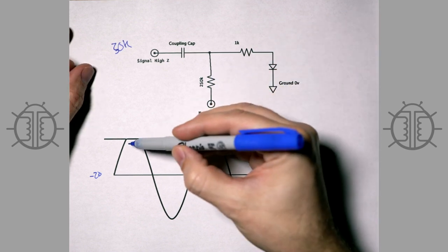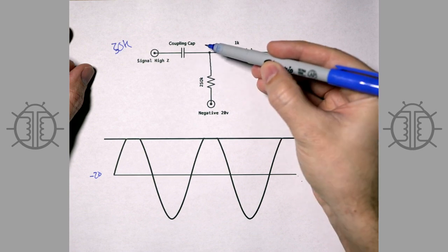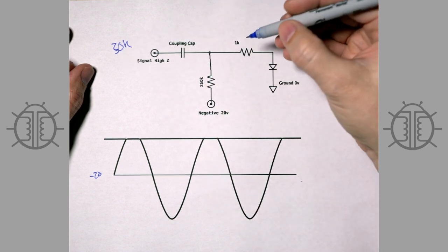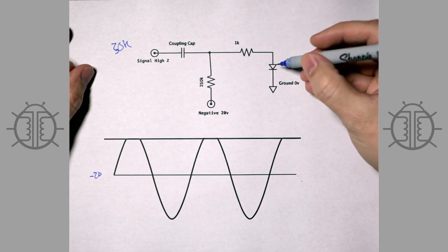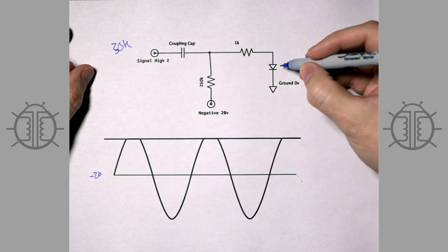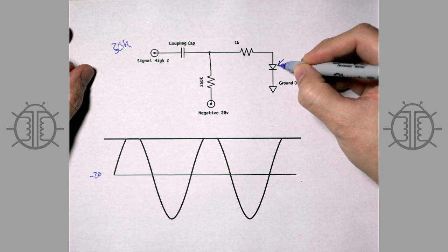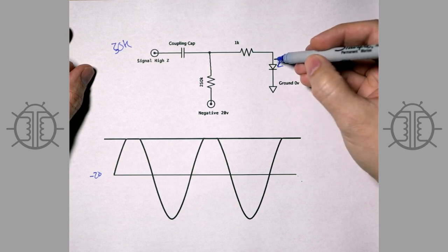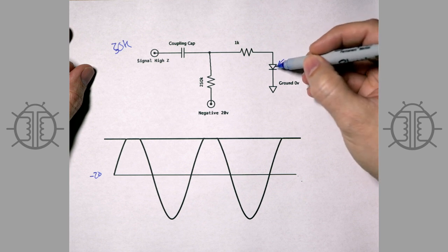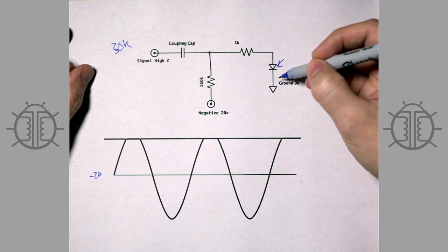But what happens is when the signal from the driver stage approaches zero and then reaches zero, this diode turns on. And so suddenly, like a switch being turned on, now the diode between a grid and a cathode is not a perfect diode.